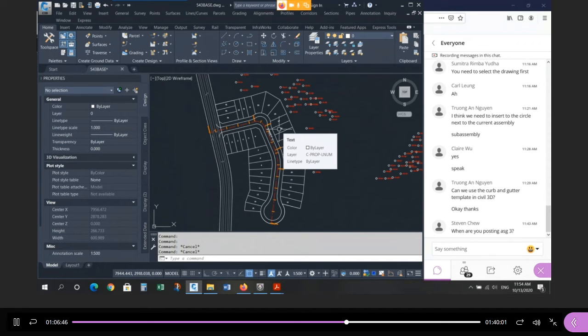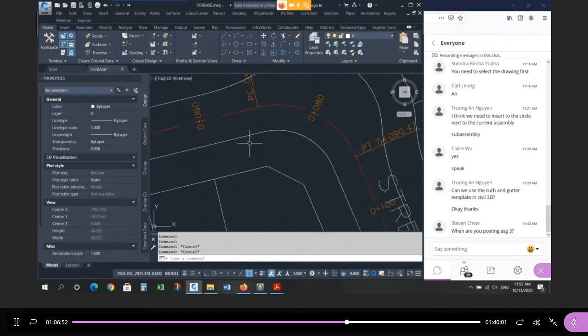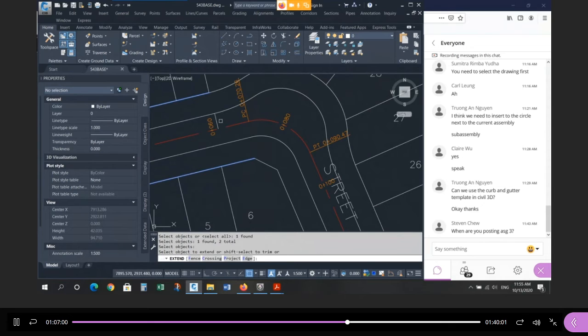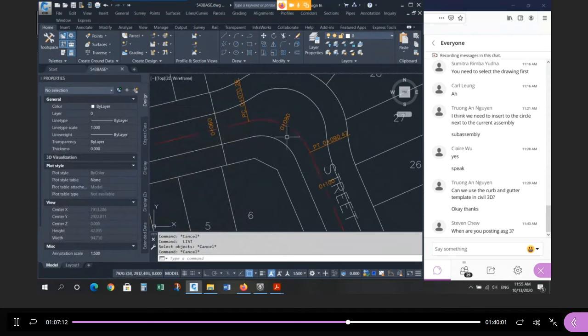Those things need to be done correctly because they have an influence on where you draw your points, right? If I want to know where this zone ends, I want to draw a line from the end of this arc, perpendicular to center. I'm going to extend that to both sides of the street line. That's the last time you have a standard 20-meter right-of-way. This is 20 meters. 20 meters. Beyond that, it gets wider and then narrow.